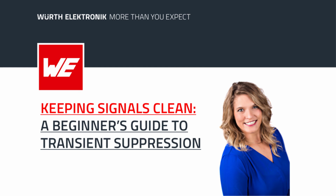Now, the requirements for the filters differ with the type of signal transmission. It can be symmetrical or balanced over two data lines, or it could be asymmetrical, which is unbalanced via one data line and the ground. Although symmetrical interfaces are characterized by low interference emissions and higher interference immunity, the signal quality is affected by transient interference signals, differential mode interference, and also common mode interference.